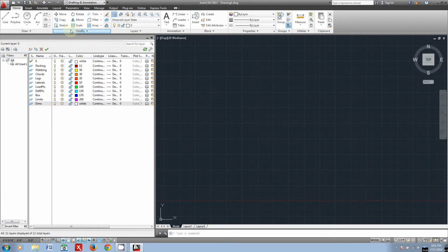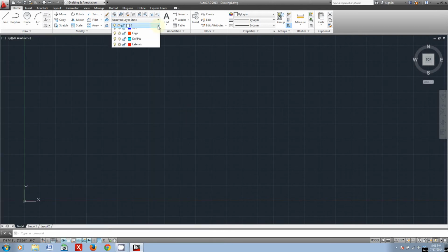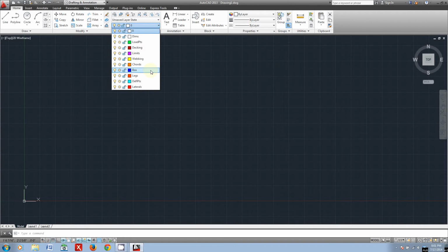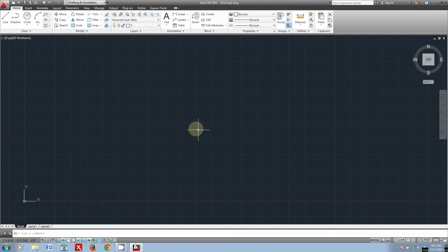So that's a good set of starting layer stuff that you can start with. You can add more, or customize it however you want to any degree of specificity. You could even specify particular tubing sizes, like if I wanted to say maybe I'd add an extra layer for 3/16 inch tubing, the really small stuff, and then you'd already know that, okay, I want these to be the smallest I can get, and then specify them accordingly. So when you open them in SAP, then you can automatically specify tubing sizes fairly easy.